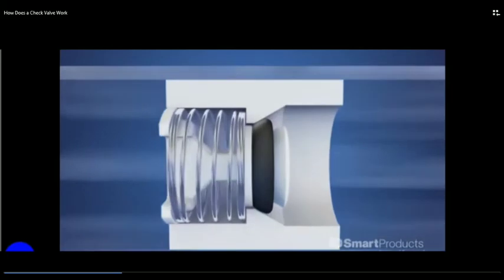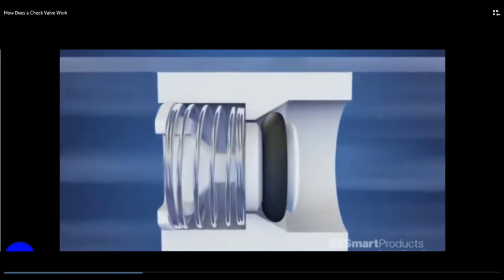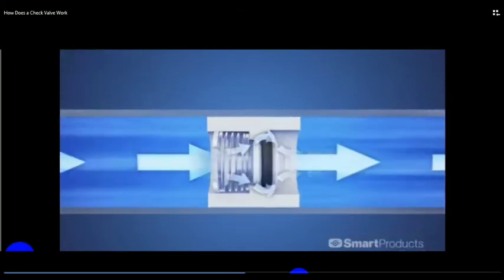Any valve that's inactive for a long time can be susceptible to leaking or stiction, where the O-ring has a delayed separation from the seat. When a valve contacts liquid or gas, certain chemicals can cause O-rings to expand, and any debris in contact with the O-ring can keep it from seating properly. As the valve starts opening, a small amount of flow escapes. Is that amount minor or significant? Knowing this helps us pair the right spring pressure with the right O-ring.